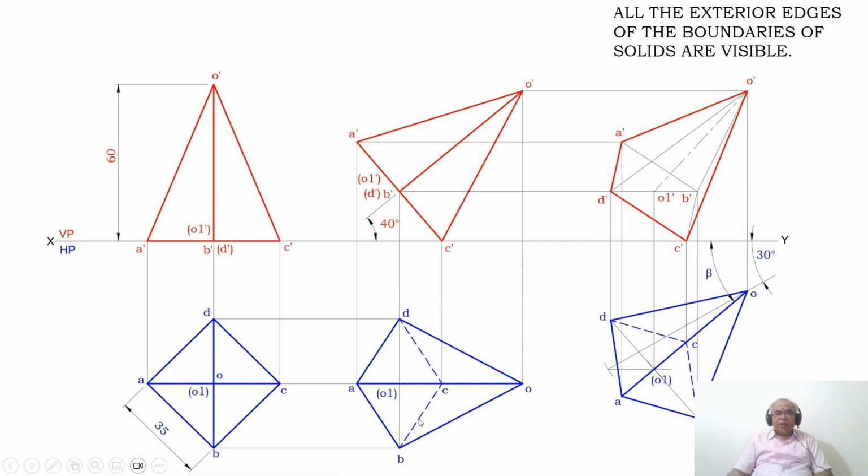But what I am trying to do now is rewrite the same sketch by rotating it at an axis angle of 30. Since this is the apparent length and the axis inclination given is the true inclination with respect to VP, I cannot rotate this on the axis line of 30 degrees, because this is the true inclination and this is the apparent length.